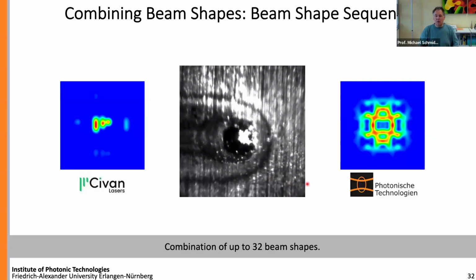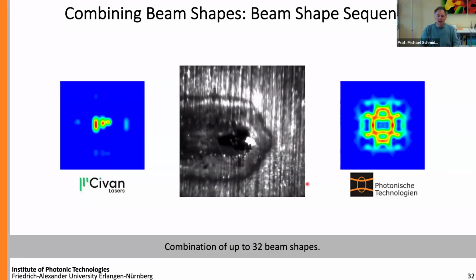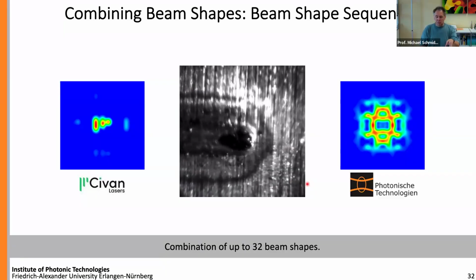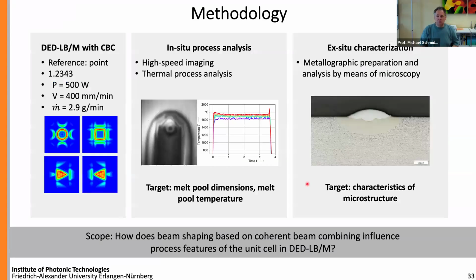So even though there's powder, we see an influence of beam shaping by manipulating, controlling the melt pool shape, which maybe is expectable. So we did some experiments on that. We programmed several shapes. Most of them you can see here, like a circle, a quadratic shape, and two triangles in opposite direction towards the feed speed.